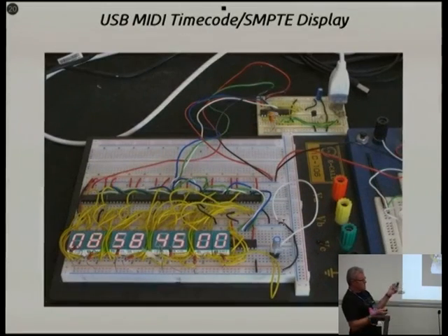And there's another one I'm working on. Not a lot I can show you there. It's basically the same thing again: an ATtiny and a bunch of TTL devices. It's going to do timecode and MIDI display, and it's going to be extended with a bunch of buttons so you can stop and set markers in your track. The idea is to have a rack mount with a nice big display, and you can use the MMC controls in MIDI, which is your play, record, stop button type of functionality, and have 10 markers within your track so you can jump between them when you're doing the recording stuff. So bringing it back out, giving you a little bit of a visual surface to work on.